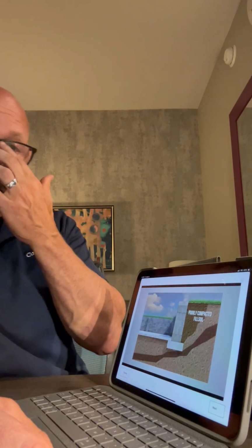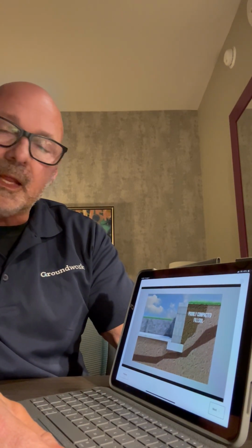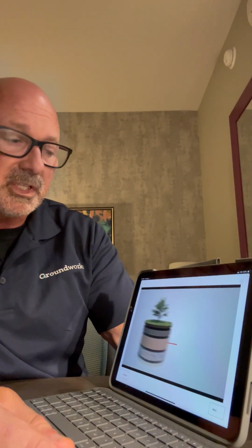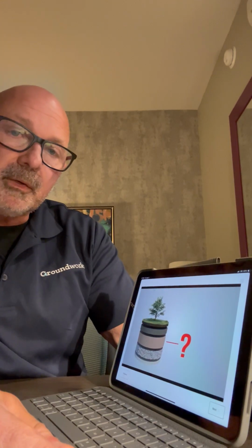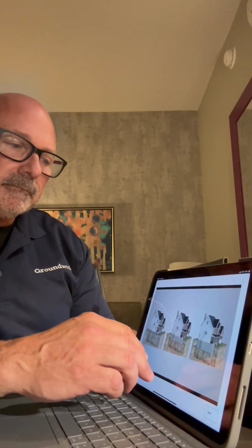And so one we don't always think about: poorly compacted fill soil. There's a strict protocol in backfilling a foundation like that, and nobody usually, or hardly ever, uses that protocol where you have to compact it in layers, so it's still loose, and that's a big problem. So any questions about that? And do you think that there's any of those three that are the biggest culprit? I know you've been living here a long time.